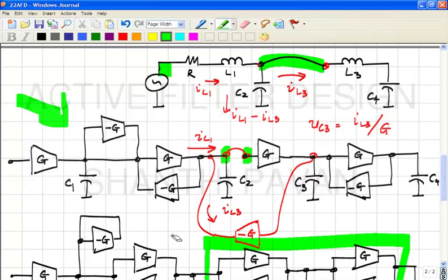When you designed the transconductors and put them in, you got 2.4 megahertz and a Q of 2.2. How will you go about fixing it? That's what I'm asking you. How will you debug it? You have a second order section with the wrong omega naught and wrong Q. They're slightly off from what you intended. So what will you do?